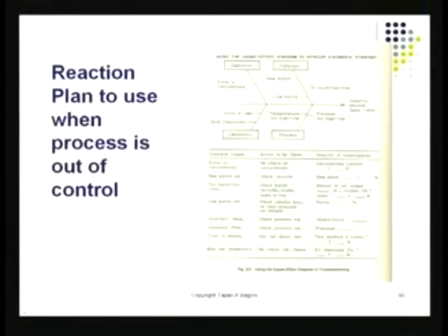What you do is you recheck your calculations. So I've listed that because it was in the cause and effect diagram. I redo the calculation, and I turn to the process and make sure that I've done all the rechecking, and I mark right here, have I found the problem? Calculation is correct? Yes. That means I need not really worry about this factor, then go down to the next one. New batch of catalyst added, is that true or false? That could have caused the problem. This is also not a problem. That means no, it's not a new batch.